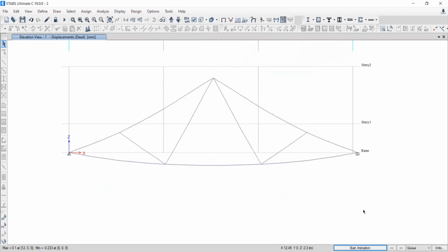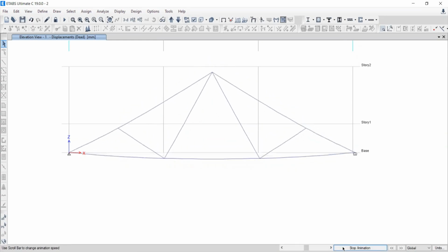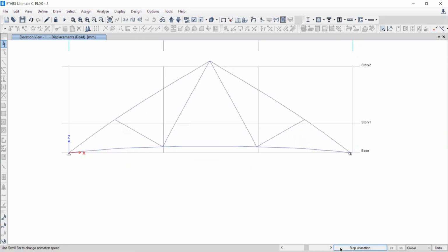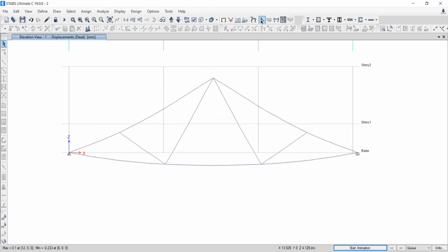For a long time we have been understanding that your fixed support cannot move anywhere. Your hinge support cannot move anywhere. Your roller support is moving along the translational direction only. So this is the proof. Your hinge support has the restraint in translational directions, X and Y, and is free about rotation.